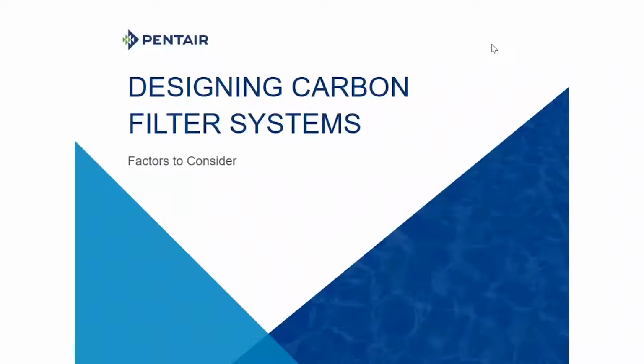Today's topic is designing carbon filter systems. This is an entry-level look at the factors you have to consider in designing carbon filters. In everything we do with carbon filtration especially, it's all based on a packed column idea of water flowing through a column of media and how long it takes to remove a specific contaminant.